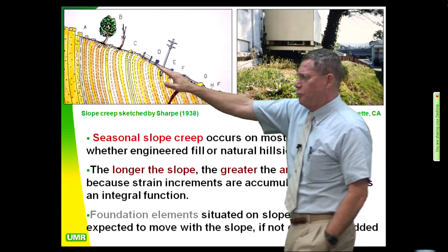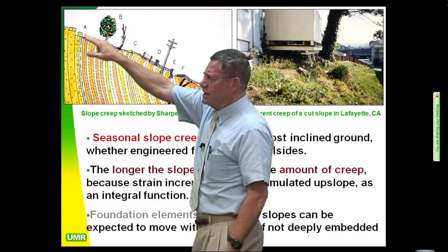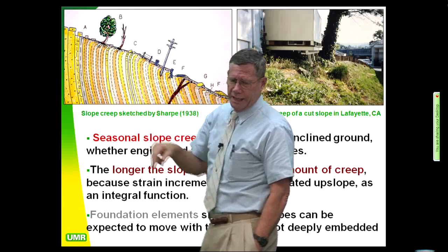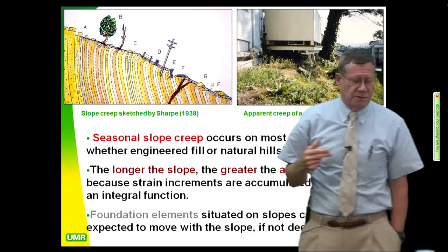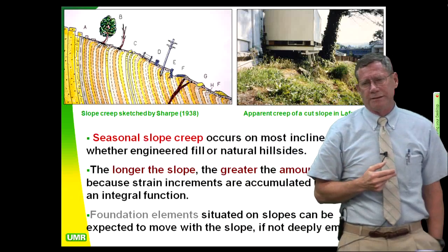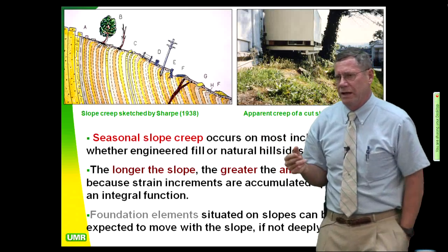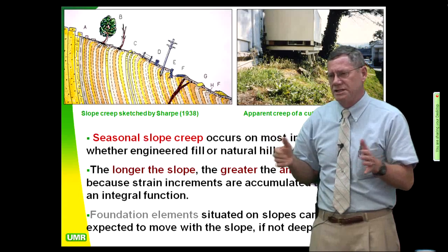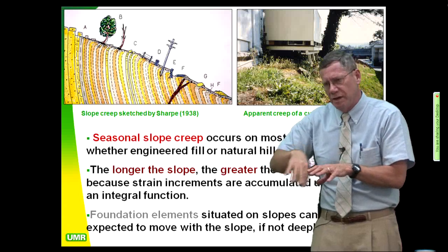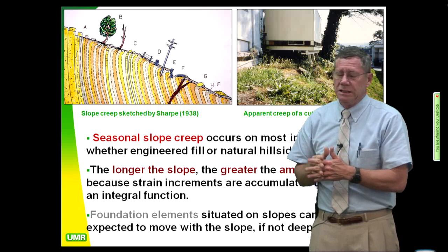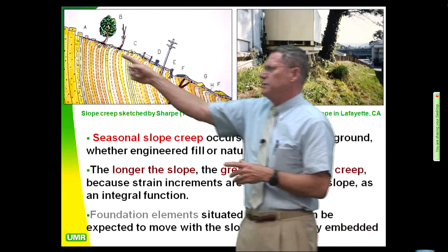And obviously if you have a point source of moisture, like a leaky fire hydrant or a leaky elbow on a water line or something, that is really going to exacerbate the situation. And you won't pick those things up with sonic velocity log testing. That only picks up the big things. You won't pick up leaks that are just weeping, don't make any noise, like you get at elbows and at T's. So you're up in the areas like this. That's a big problem in Honolulu.